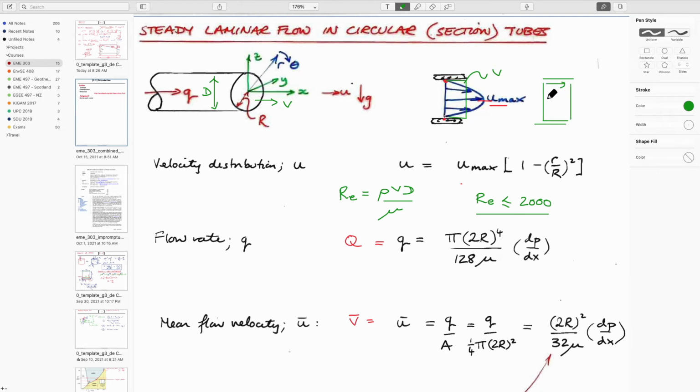So these would be the velocities. Instead of being zero velocity here, it will be zero velocity here, but with a very sharp transition. I can't draw it well enough. It would be like this. So this would be the flow velocity for a Reynolds number greater than 2,000, and this would be a Reynolds number less than 2,000.